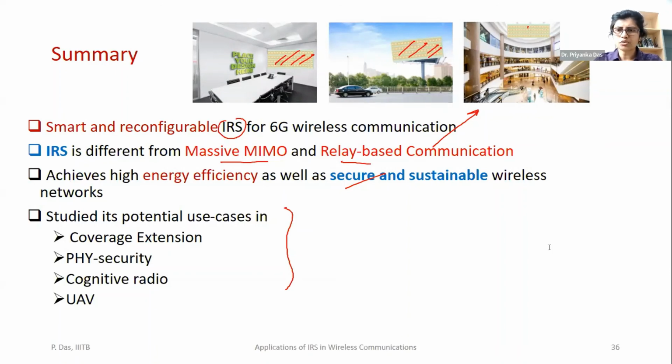The parameter is the channel. The IRS controller will sense it. In the next step, I will tell you how the channel estimation is done. Basically, you need to capture the channel phases. Depending on the channel phases, you need to determine what will be your theta i, that the controller has to tell the base station and IRS.